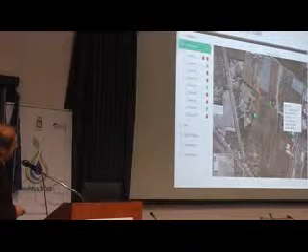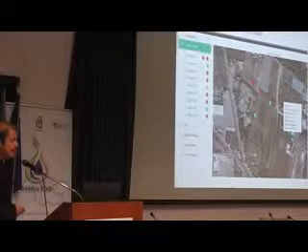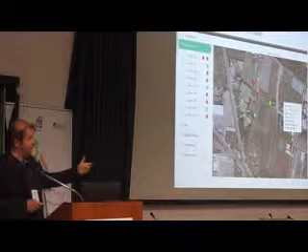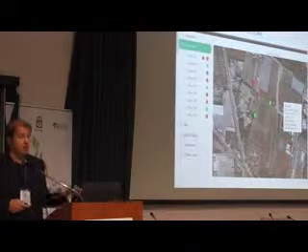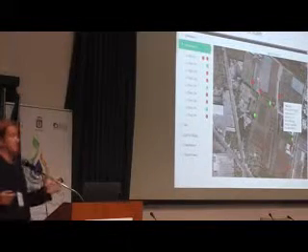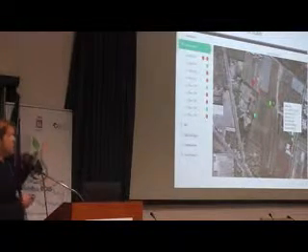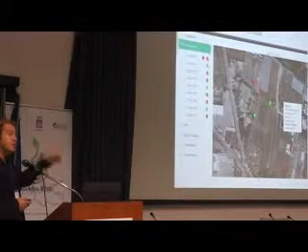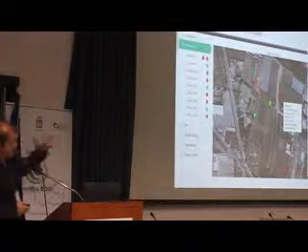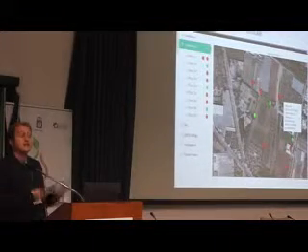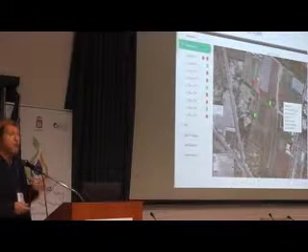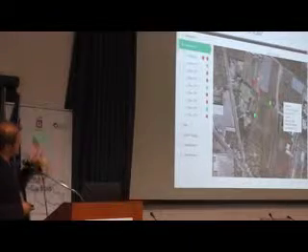You see these green hydrants are open, these red hydrants are closed, and you can directly, or through your mobile phone, or through your computer, close and open each of the hydrants. You can send orders to say where to irrigate. You can program your irrigation from that hydrant, telling that you would like this hydrant to irrigate 10 cubic meters starting from 12 o'clock until 2 o'clock and so on. So you could have full control of the system at district scale.